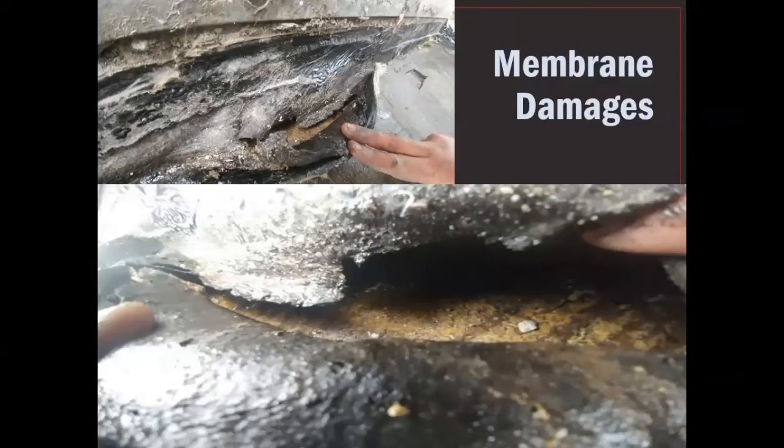Other membrane damages we see on the balcony surfaces, we see a lot of issues with the stripping or the flashing membrane on these surfaces. These areas in particular can be weaker points just because of the natural movement of the building. We tend to see issues with the stripping or the flashing before issues with the field.